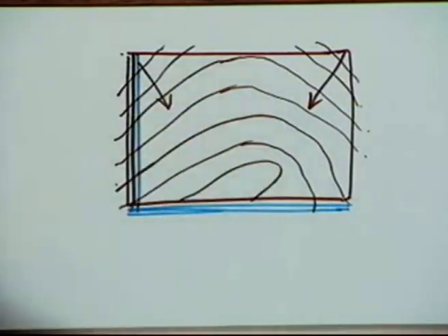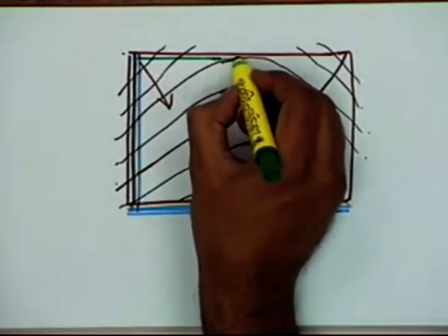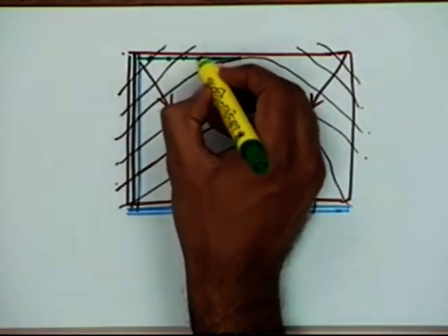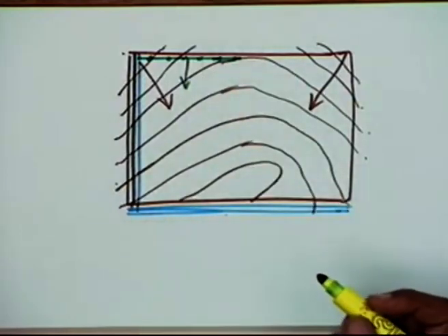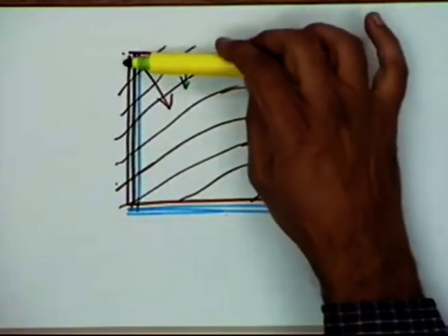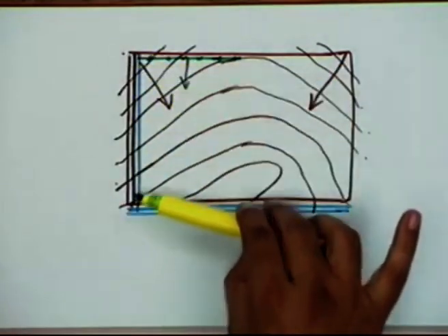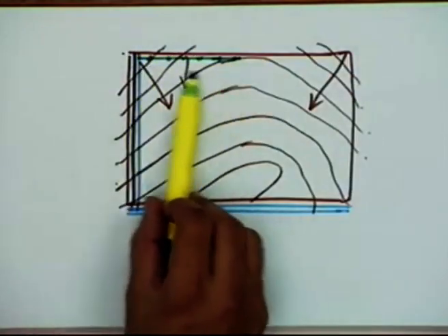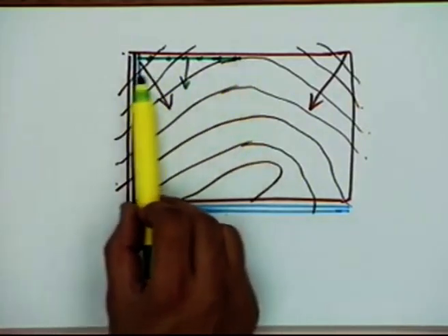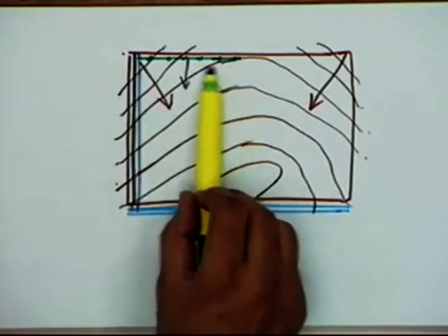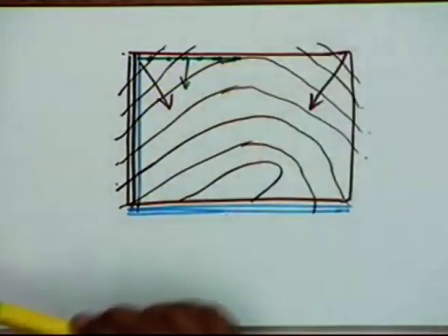Now from here I can have the lateral which is having the sprinkler heads, and that can be moved in this direction. Now the advantage is that in this particular case your main line is laid on one side, and you are still taking advantage of the fact that there is some downslope, there is some pressure recovery which is possible, if your lateral is laid down in this particular manner, on this side.